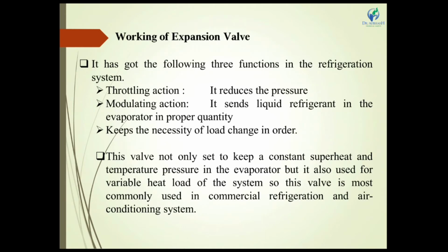The major advantage of this expansion valve is that it controls the pressure and temperature of the cooling side, meaning in the evaporator. So it is mostly used in heavy air conditioning systems. Heavy air conditioning systems are mostly used in commercial refrigeration systems and air conditioning systems.